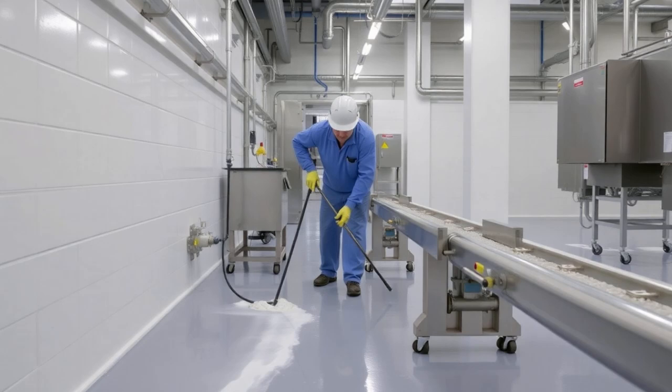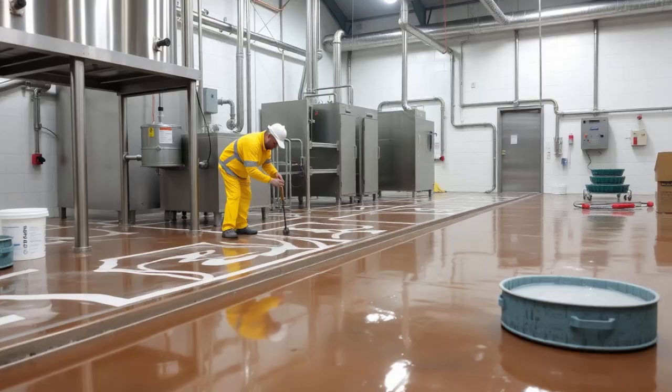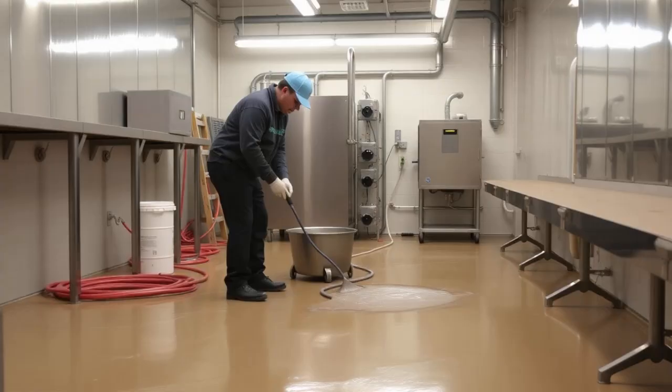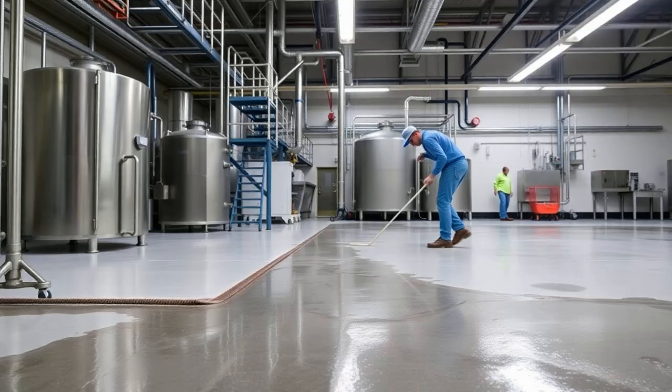But when applied in a food processing plant, this is a critical area where water resistance and chemical protection are required. So in the food processing plant, you cannot use the cementitious grout. You have to go for the epoxy grout. There is no other choice. Where you are using it is important, and what the intended purpose of use is. According to that, you need to choose the grout for your projects.